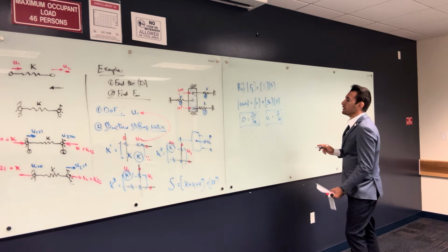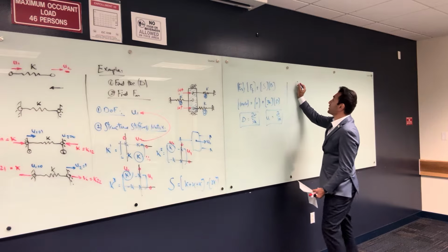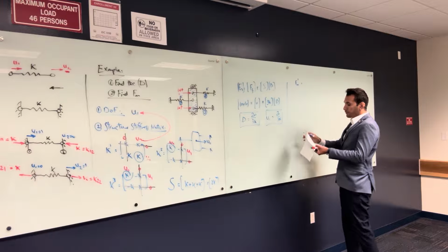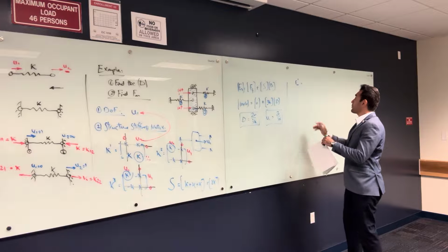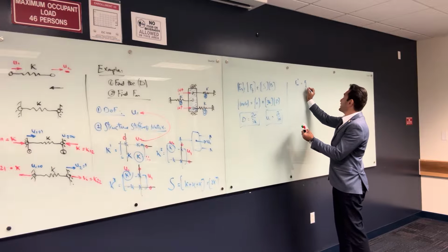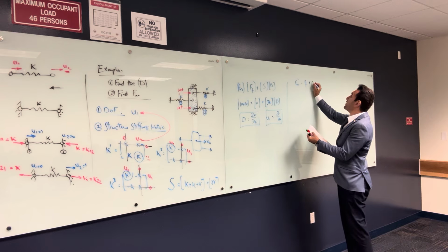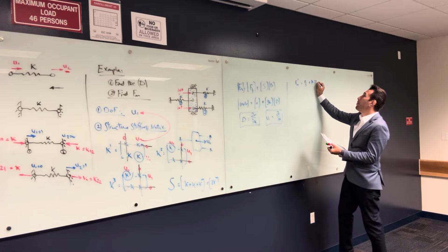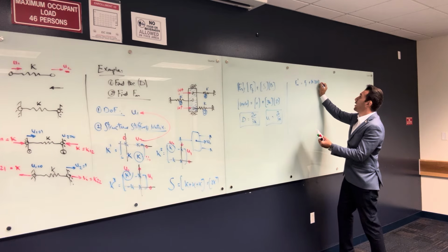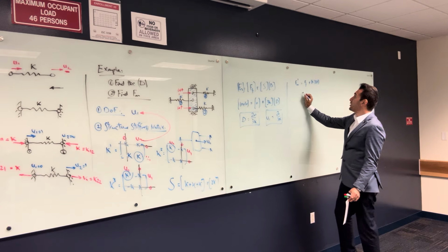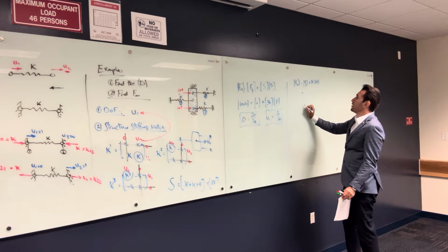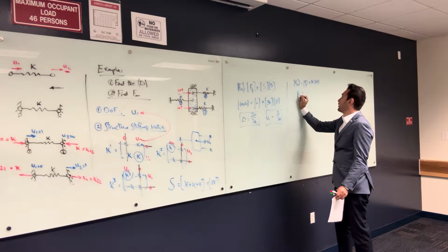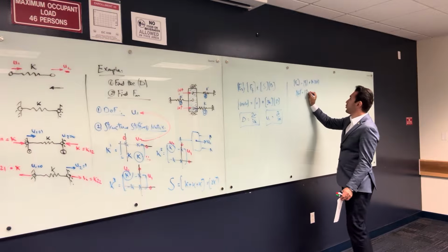But let's actually solve this using the stiffness method. If you want to find the force of any member, F member number 1 is going to be equal to the F fixed end force, which is 0, plus the stiffness matrix of the member. By the way, this was the structure. Right now we are talking member, multiplied by the U or D at this member. Okay, so all this is matrices and vectors. So this is 0. This is what I'm looking for.